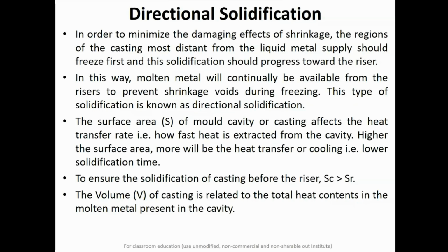And as you all know, the surface area of the mold cavity or the casting affects the heat transfer rate. It means that the more the surface area, the faster the rate at which heat is extracted from the cavity, and the casting will experience more cooling and will have a lower solidification time. And to ensure the solidification of the casting before the riser, the surface area of the casting should be more than the surface area of the riser.